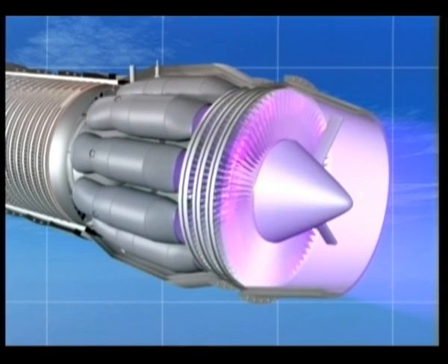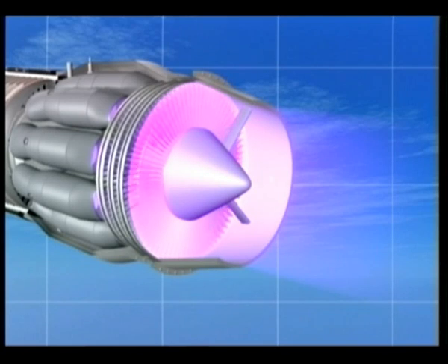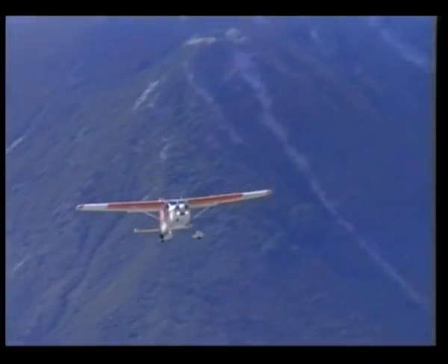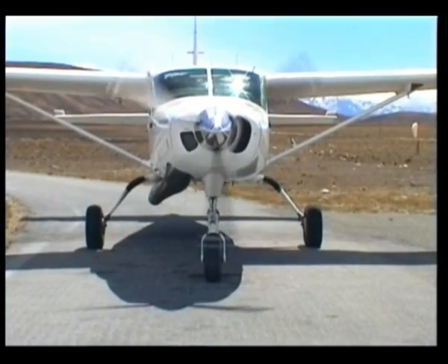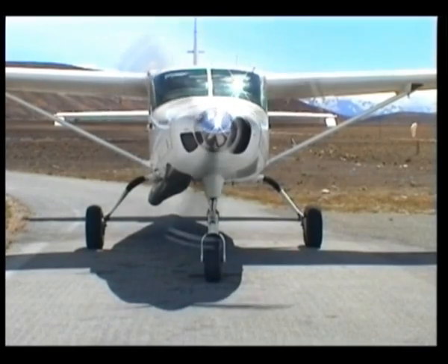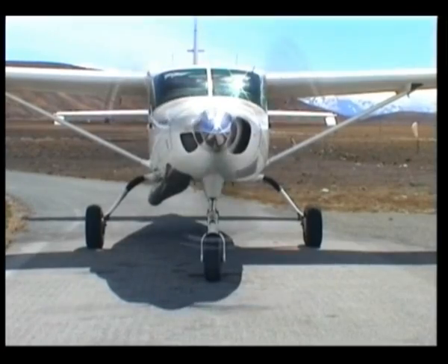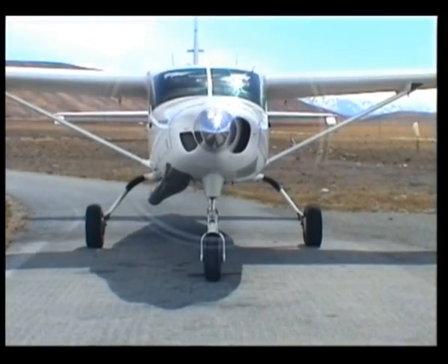A turbojet-powered aircraft obtains thrust by accelerating air through the engine. It is the reaction to the rate of change of momentum of the mass of the air that propels the aircraft. Like a piston engine, there is induction, compression, ignition, expansion, and exhaust. Unlike a piston engine, the process is continuous. A feature of the gas turbine engine is the use throughout of convergency and divergency, the increase and decrease of velocity, pressure and temperature through the use of ducts.